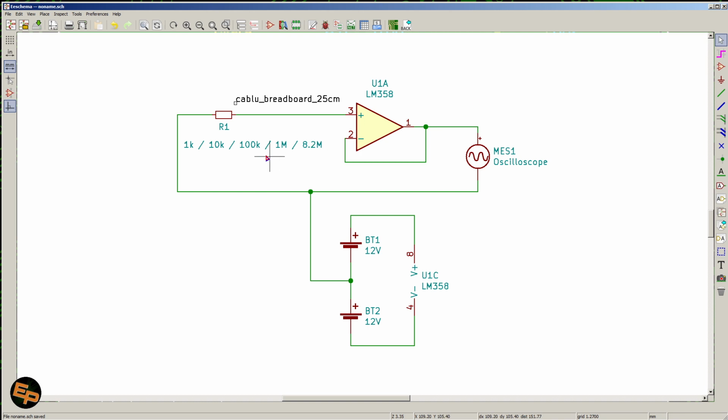When the impedance cannot be made smaller, we either have to think about using shielded cables between the part of the circuit that provides the signal and the next stage, the next circuit.